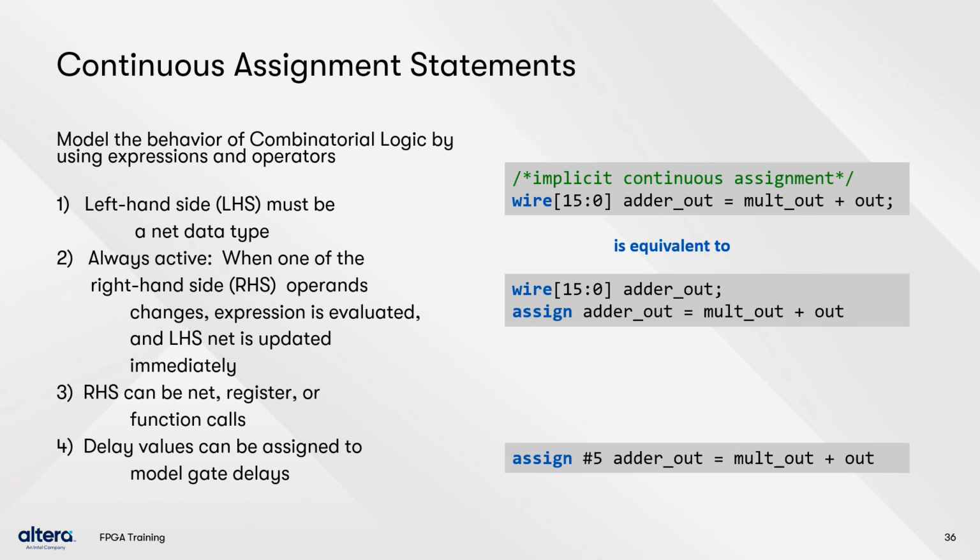In a simulation environment, delays can be assigned to the assignment to model actual gates. In the example given, assign #5 adder_out equals mult_out plus out. If mult_out or out changes, then adder_out will be updated with appropriate changes 5 time units later.